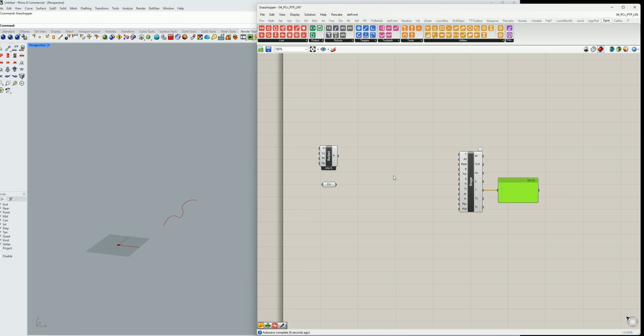So what's the first thing we want to do? Let's go ahead and use the Path Curve, which is underneath the toolpath. It just automatically takes the curve and turns it into toolpathing. You can see the LIN commands already there. We can adjust different things, such as dividing the curve based on distance. So if it's 100 millimeters and you divide it by 5, you get 20 reference points. If you want a very smooth curve, with smaller intervals, you can increase that up and down.